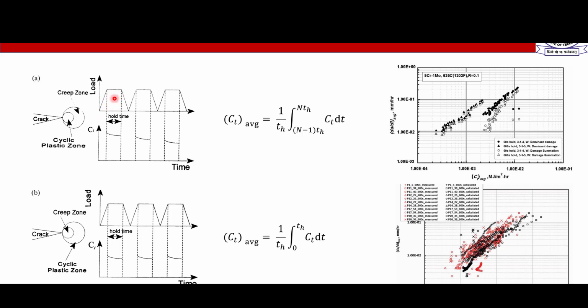So just remove the square thing from the middle. So you load it, unload it like a simple fatigue cycle, and you will be having some creep also. Okay. You can have it in different ways. You can also do it sinusoidal and other things. But mathematically, it is simpler if you have a trapezoidal form, and this is why you will find a lot of work on trapezoidal waveform.